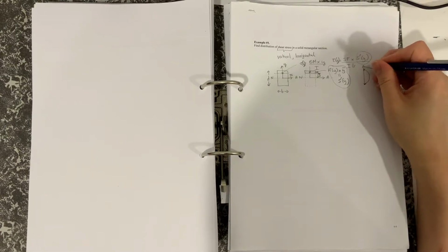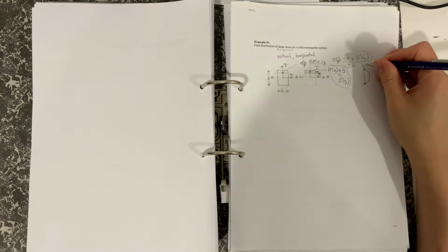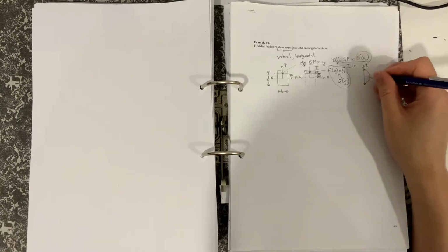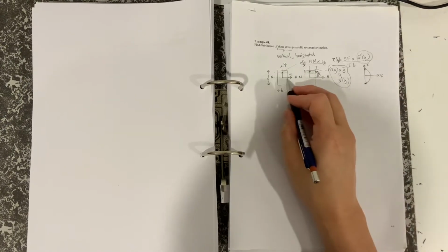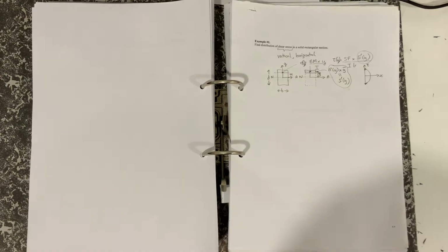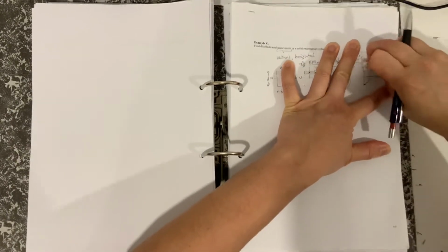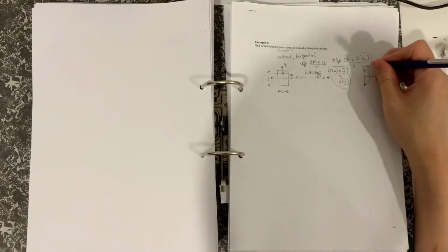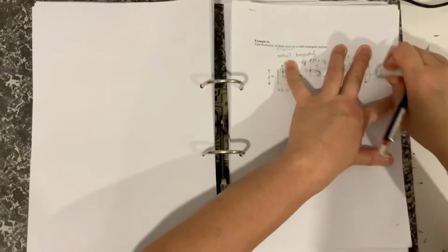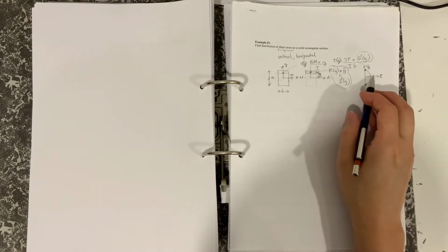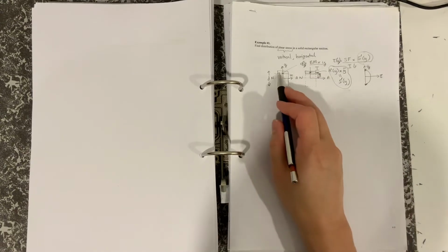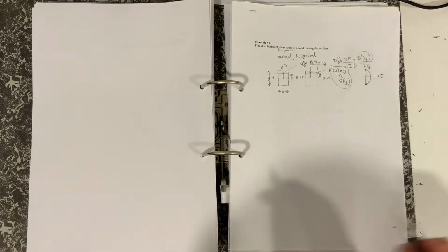So I could put that as a plot of tau, and that is going to be your x-axis. So that's a cross section. So that's the x-axis there. Sorry, got that wrong, haven't I? That one would be y. Yeah, that one is obviously y, and then this axis here would become your tau. Okay, so the tau, the shear stress, whether it's vertical, horizontal, it's the same at any line across here. It would be the same.